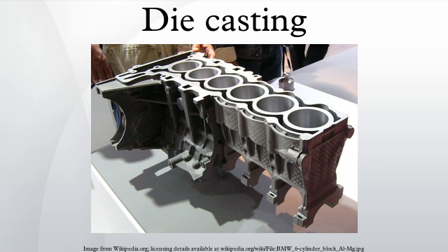Pore-free. When no porosity is allowed in a cast part, then the pore-free casting process is used. It is identical to the standard process except oxygen is injected into the die before each shot to purge any air from the mold cavity. This causes small dispersed oxides to form when the molten metal fills the die, which virtually eliminates gas porosity. An added advantage to this is greater strength. Unlike standard die castings, these castings can be heat-treated and welded. This process can be performed on aluminium, zinc, and lead alloys.